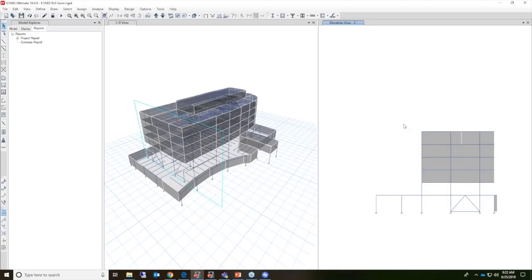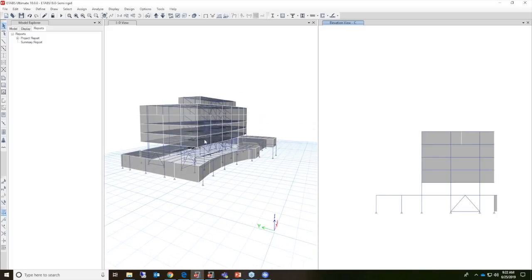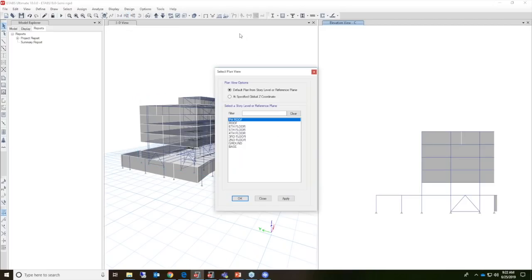Okay, look, so it drew some cladding on the structure, but you'll notice that cladding was not added to this floor here, the second floor. And that is due to the fact that there are area objects located on the perimeter on the floor below, so it didn't recognize the location. So that's fine. We can make changes to it very easily. So what we can do here is we'll go to the second level and apply cladding now using the beam elements. So if we click on plan view, and I think it's the third story, let's take a look.